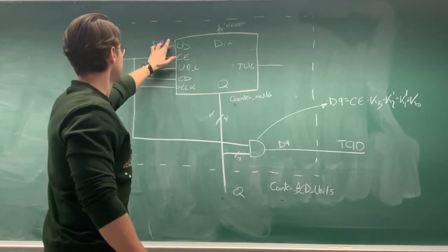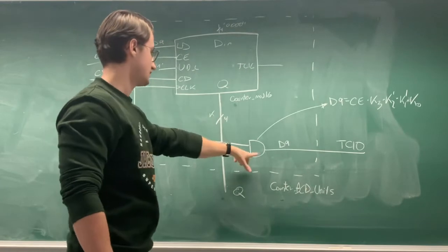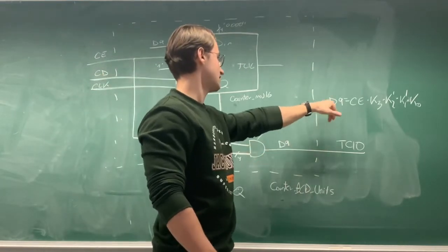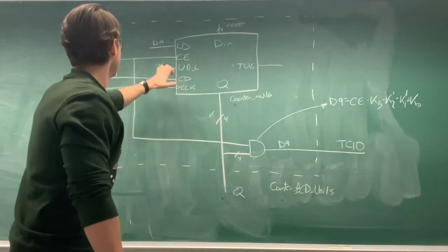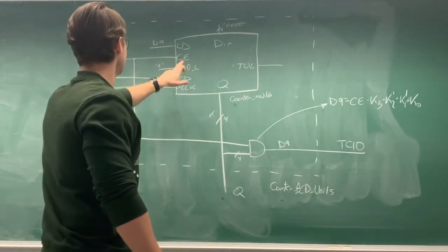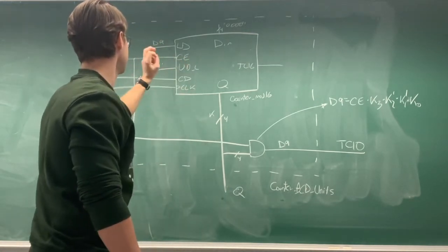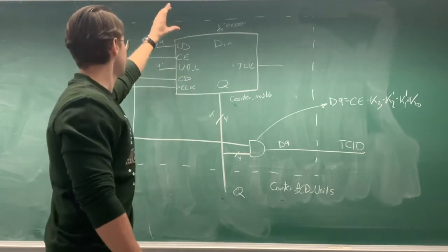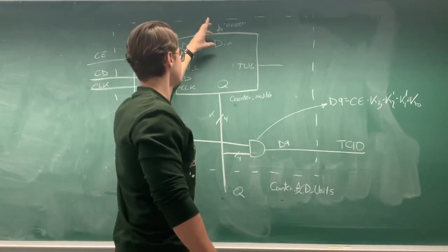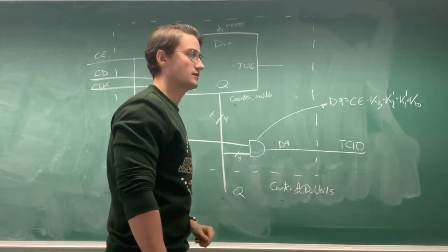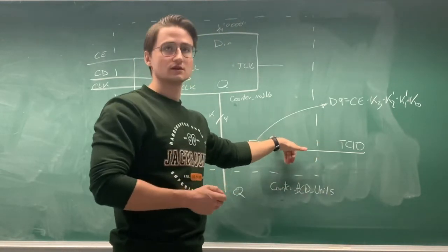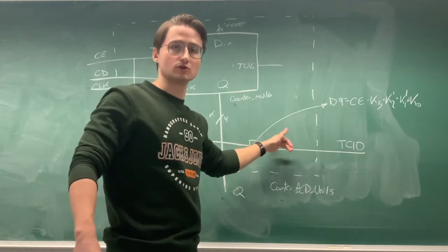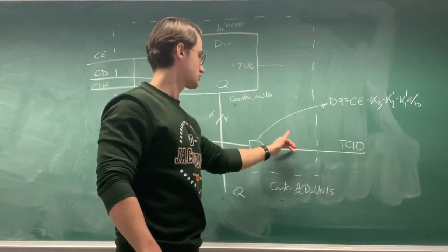It has the load that depends on the logic of D9, which is an AND gate that depends on the count enable and the output. The count enable is always 1, plus the clear direct and the clock. Whenever the load is 1, we input all zeros to reset it again. And then we have TC10, which is active when the 9 is detected, so that it can allow the counter modulo 16 tens to start counting.